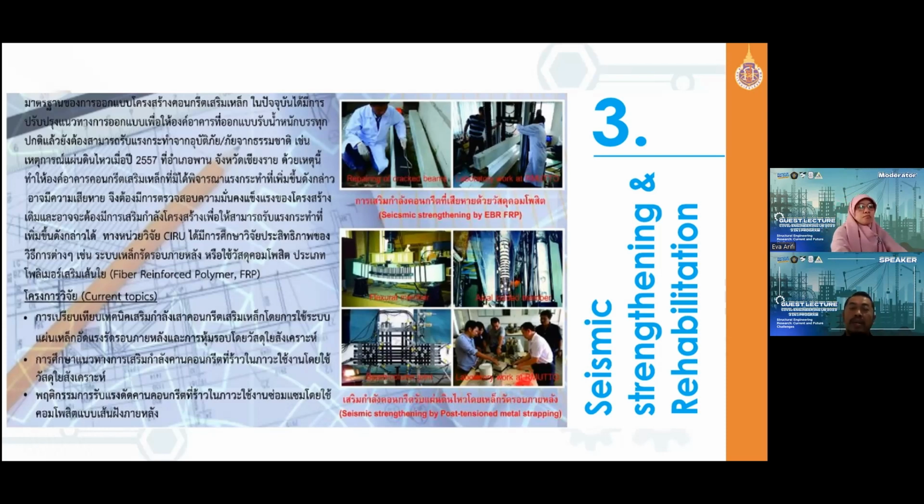We did not expect an earthquake to happen, but in the last 5 years, we had a very strong earthquake in the north of Thailand, in Chiang Rai province, if you heard about it. I went there as a structural engineer, and it's impossible to remove all the houses or buildings and rebuild them according to the new code. So we need to do some strengthening. Mainly, you try to improve ductility, deformability, and also capacity. Sometimes you can't improve capacity much, but you can improve ductility.